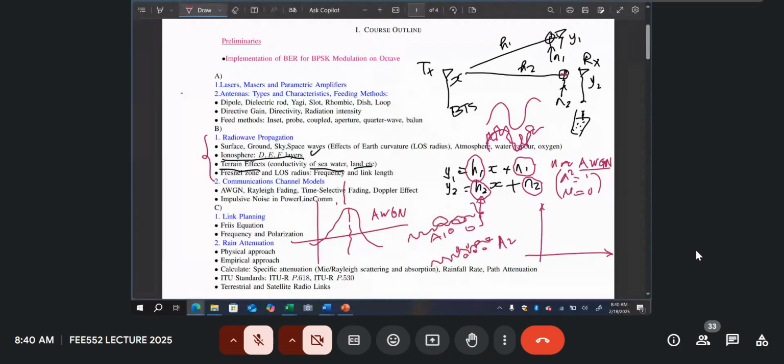So it means when we do our distribution, we realize that it goes like that and then has a longer tail because of much absorption. So in this case, then this can be called a Rayleigh PDF. So it means then in rain attenuation, we can consider H, that is a Rayleigh PDF. A Rayleigh PDF now is not going to have this bell shape. It's going to have that tail that is lagging there. And the distribution function is different.